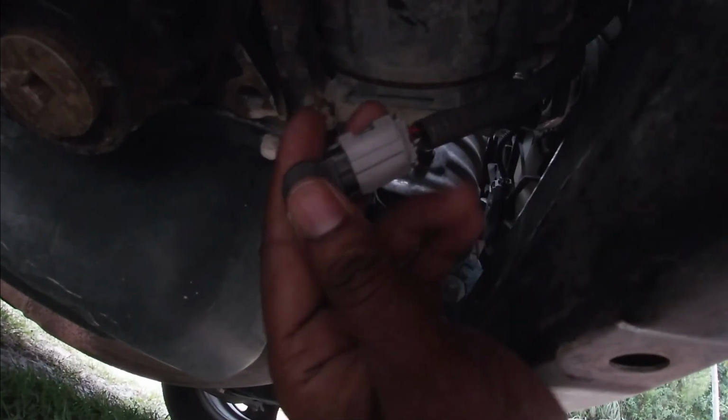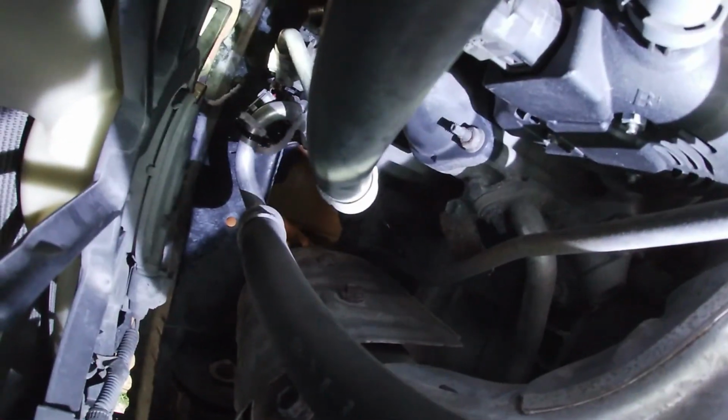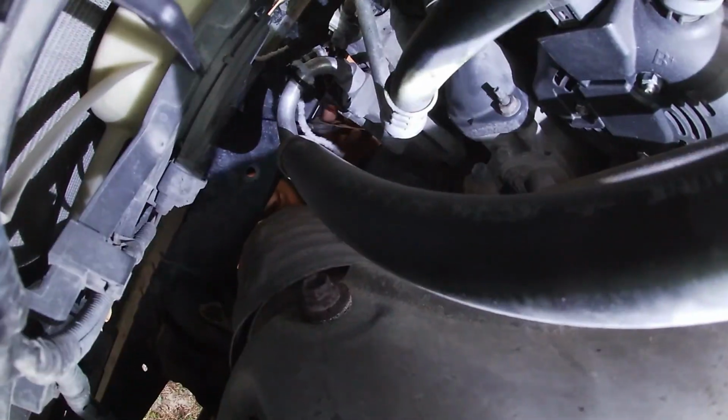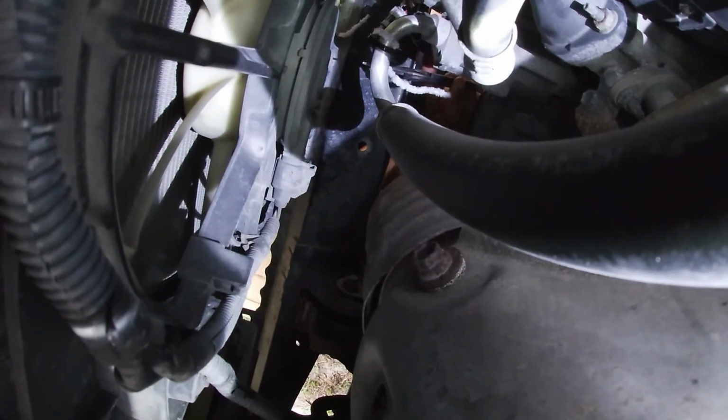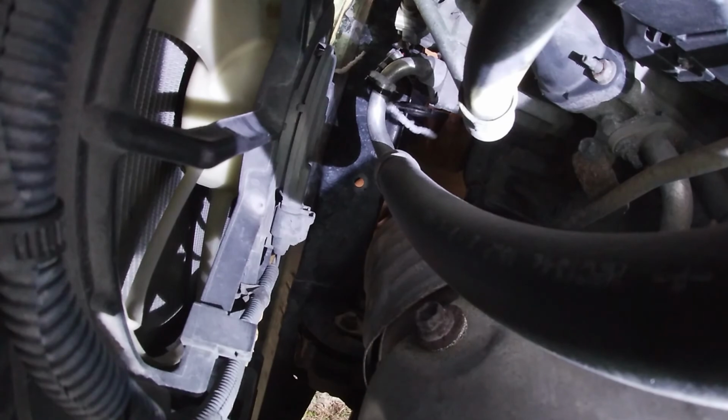I left the old sensor in the car on the compressor itself. I left it on the compressor because you cannot remove it. It's held in with a C-clip, so to remove it, you need to remove the compressor. So what I've done here was I zip tied it to the refrigerant line. I saw someone put a photo somewhere on the internet about doing this, and it worked perfect.